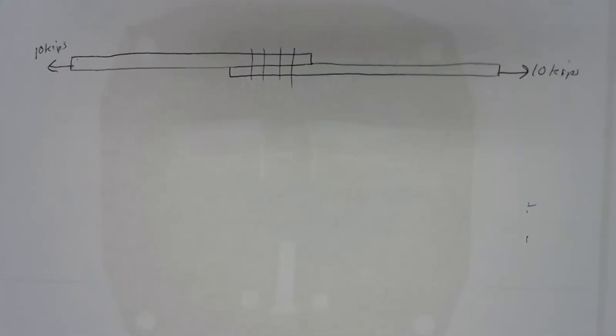You're making it so that their areas don't necessarily add up entirely. As long as the rivets are far enough apart and far enough away from the edges, we can count each rivet as acting individually. So it makes it easy to total up the area. When you put them too close together, you get stress concentrations and you raise the likelihood that the base material, the aluminum, is going to break before the rivet shears through.